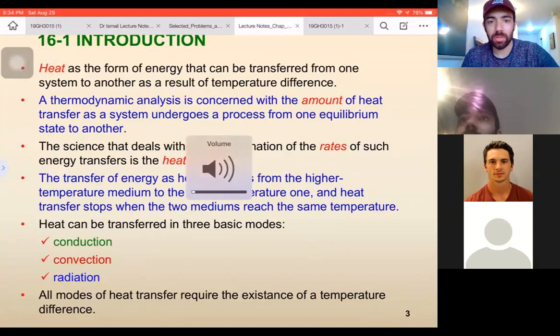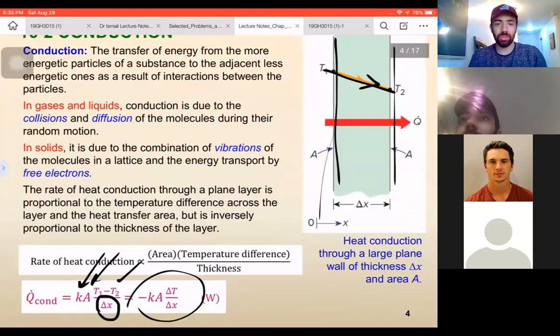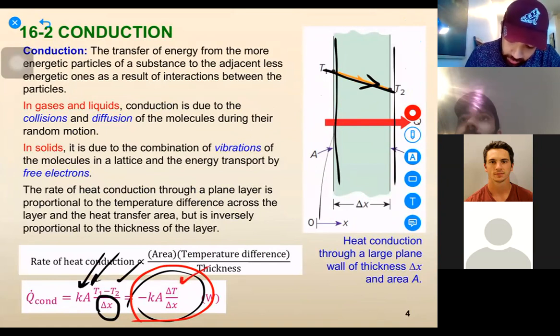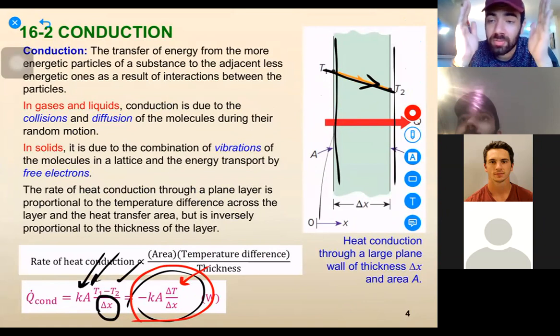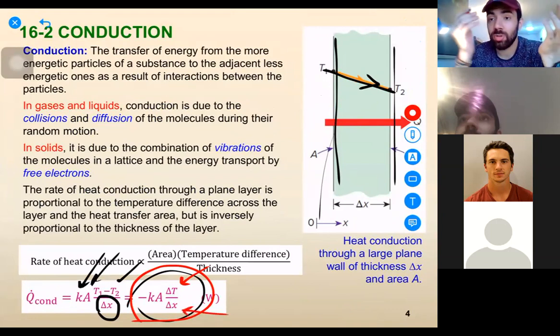We covered the terms for conduction. For conduction, we had, let me use my pen here again, these 4 terms: the constant of conductivity, the area of the surface you're talking about, the temperature difference in the numerator, and only one term, which is the length or the distance between those 2 plates, in the denominator, that is affecting the total heat rate in an inverse manner.